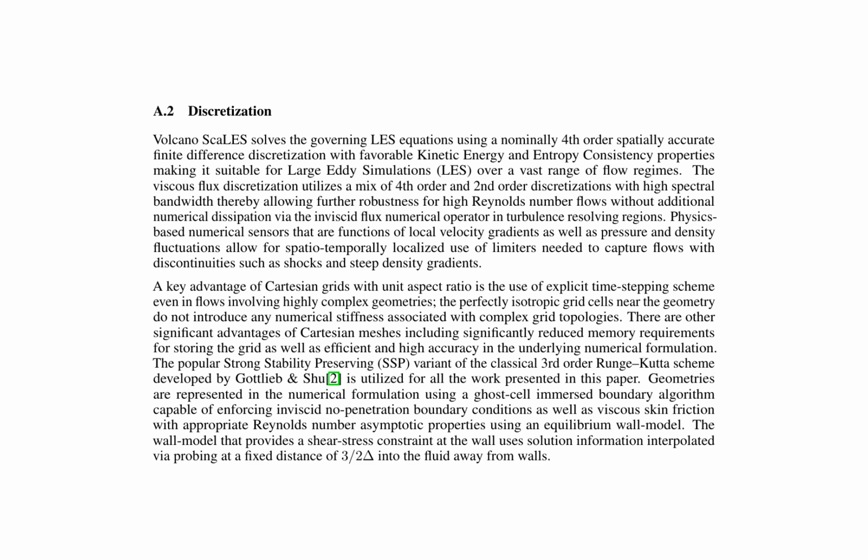Physics-based numerical sensors are employed to capture flows with discontinuities, allowing for accurate modeling of complex flow phenomena. The use of Cartesian grids with an explicit time-stepping scheme enables efficient and accurate simulations, even in complex geometries. This approach offers several advantages, including reduced memory requirements and efficient numerical formulation.